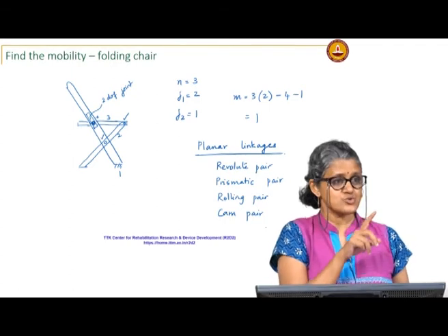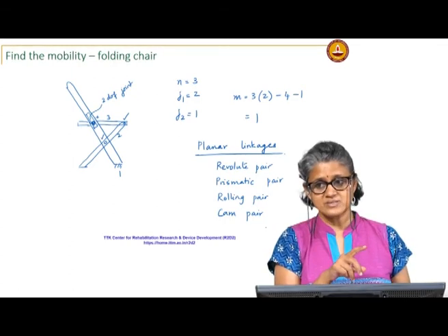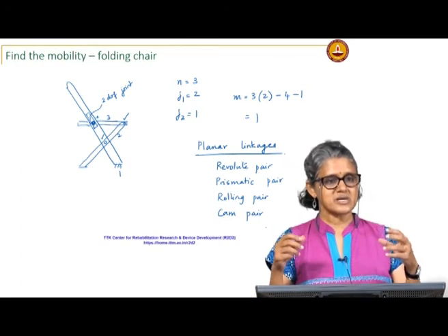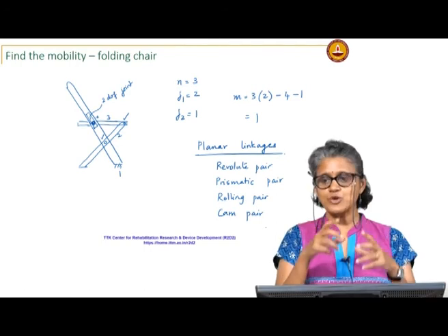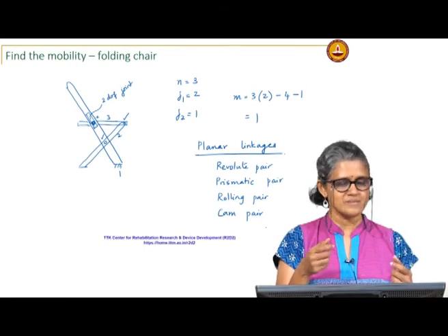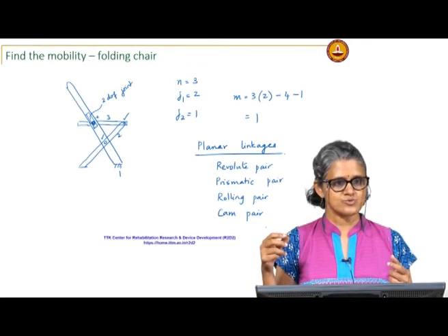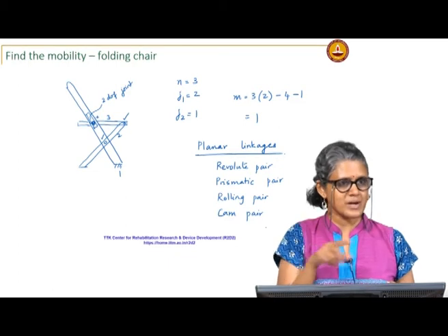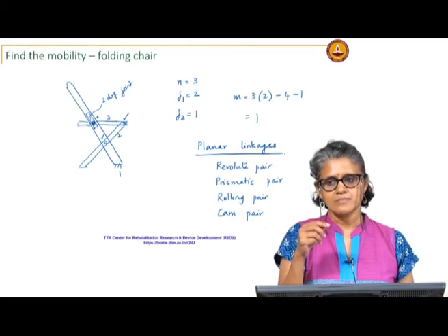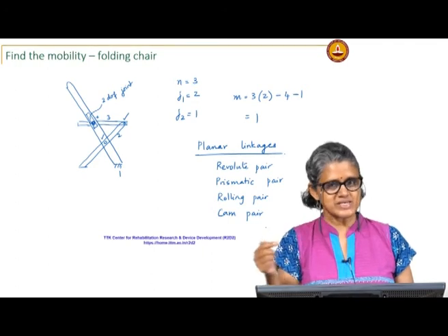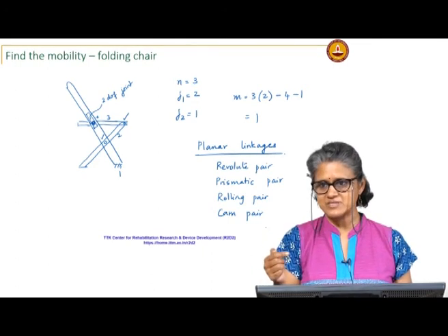You will find screw joints in many applications, but they will be used for things like a one time adjustment. So, if you look at a pair of pliers, cutting pliers, right. Many of them will have a screw joint. So, the pliers, if you look at it, it is essentially a 4 bar linkage, but you will have one screw joint here which will basically adjust one of the fixed pivots.